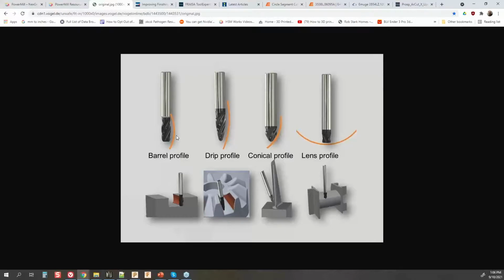And that also means when you're selecting your cutters, you have to keep your geometry in mind, how you're going to reach down into the cut, how much clearance you have on the angle, and of course the surface radius itself, whether or not the radius is going to fit within the profile of the cutting tool. Now, all of the cutting tool manufacturers do have ways, and on their websites they have different things that help with the selection of these tools, and we'll touch base on a few of those things as we go through the demonstration today.